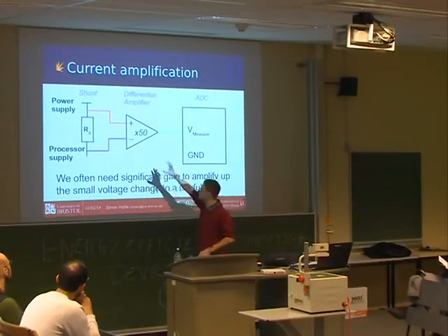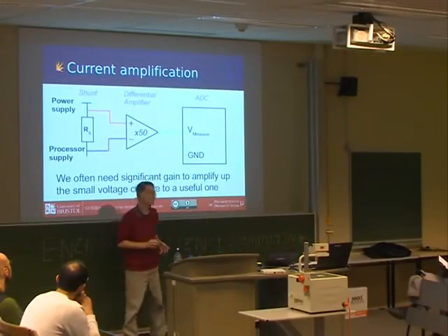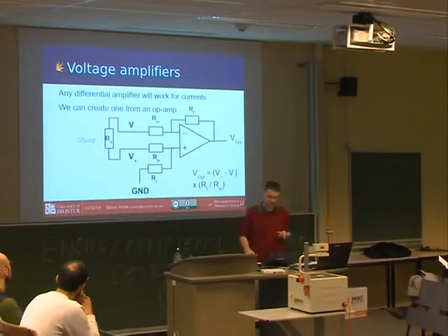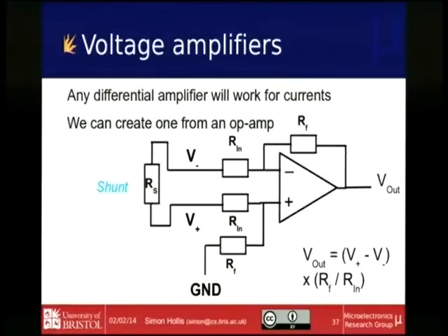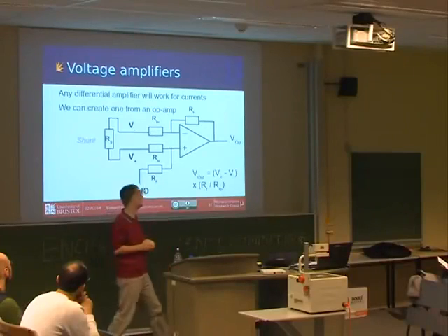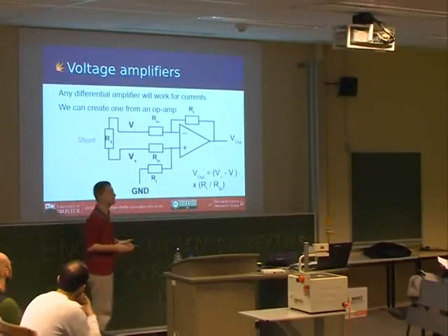So your question then is, how do you build that differential amplifier? Well, that's the stuff of electronics engineering students the world over in their first year. You can use this device called an operational amplifier, well known, well tested, very easily available off the shelf, and you build exactly this circuit. So you've got 3 connections on the device: a differential input, an output, and then you add in this simple feedback,